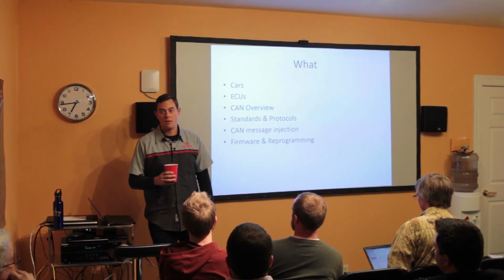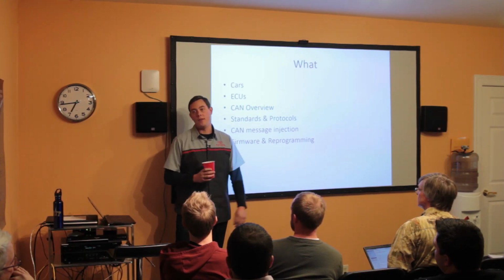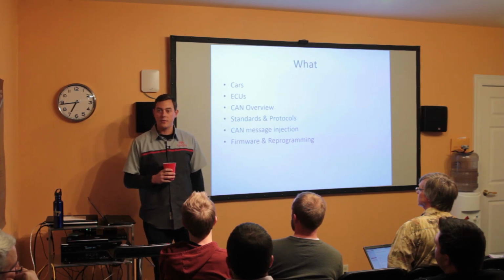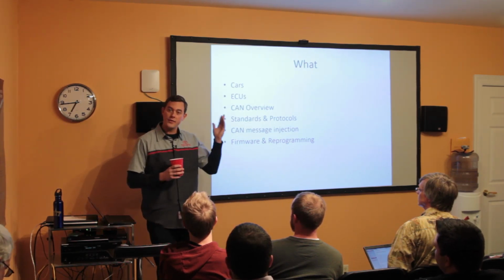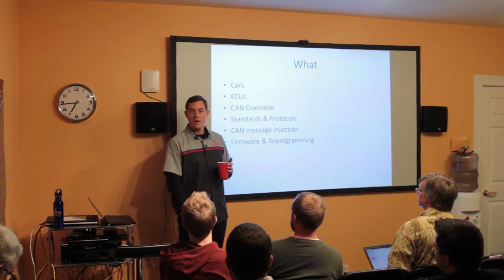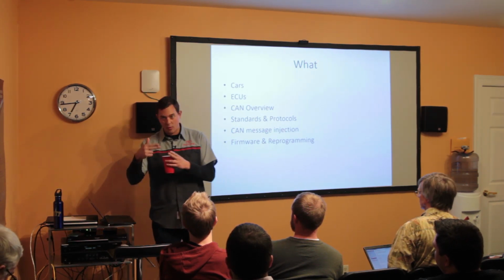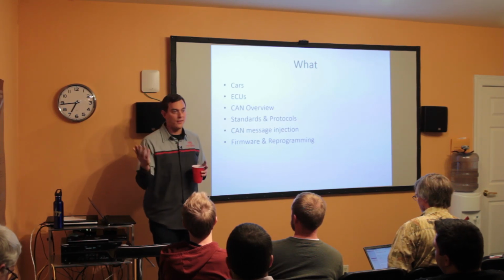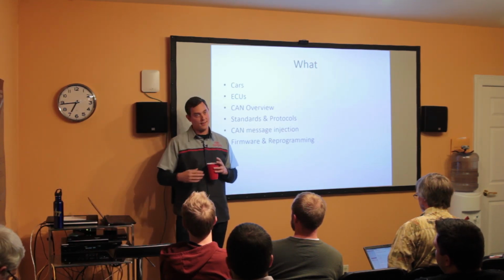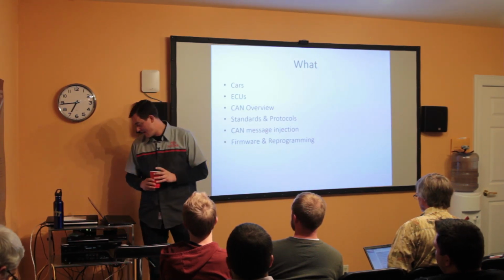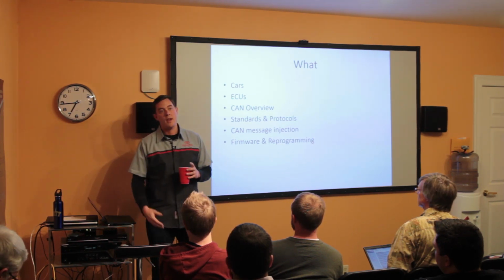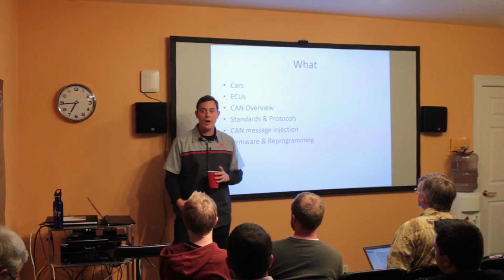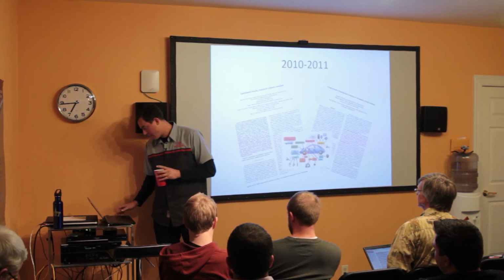Is this limited to OBD2 port access? No. As long as you are on the CAN bus, whether you hacked in wirelessly through Bluetooth or telematics like OnStar, OBD2, or you physically clip two wires to CAN high and CAN low, it doesn't matter. As long as you're on the CAN network, it's the CAN network, right? And finally, we'll show you how we got the firmware from some of these ECUs, reversed them, did some reprogramming, and actually got persistence on the car as well.